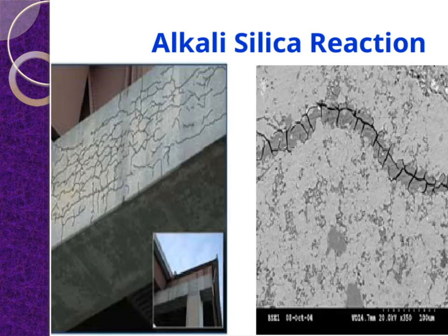Let's talk about alkali-silica reaction, or ASR for short. This is a chemical reaction that can occur in concrete when certain silica-rich aggregates come into contact with alkali hydroxides in the cement paste. Essentially, the alkalis in the cement react with reactive silica in the aggregate, forming a gel that can absorb water and swell over time. This swelling creates internal pressures that lead to cracking and deterioration of the concrete. It's a particularly insidious issue because it often develops slowly and can be hard to detect early on.